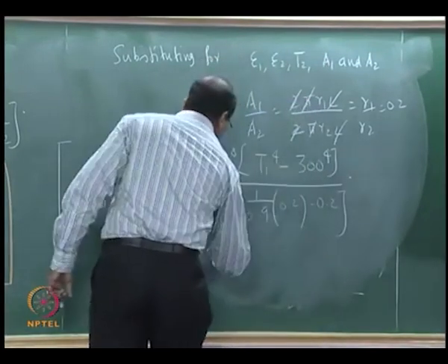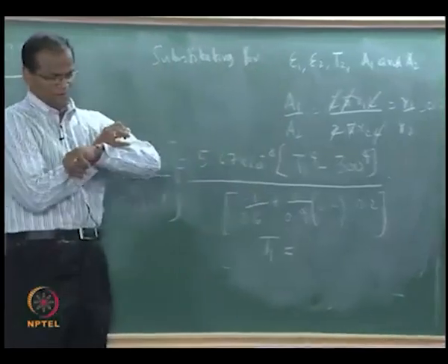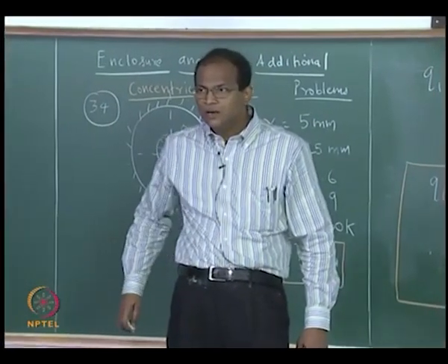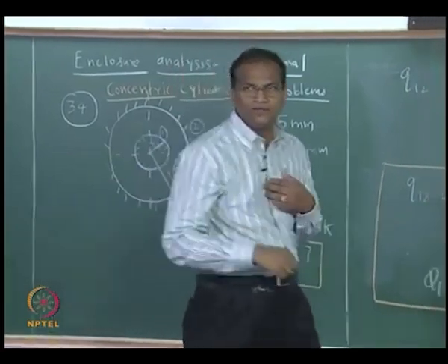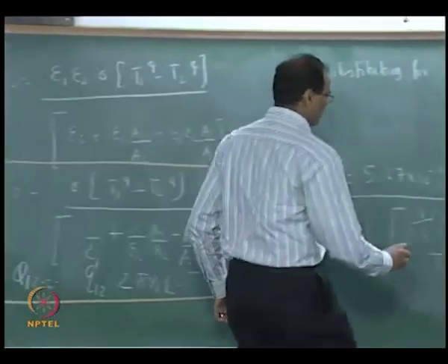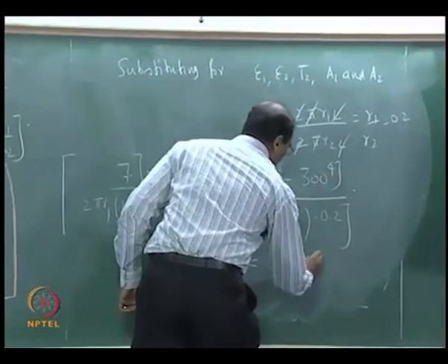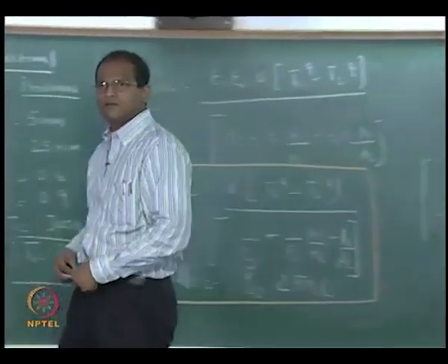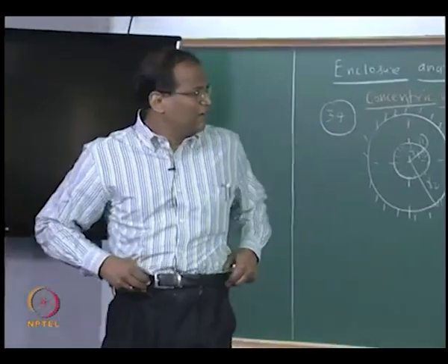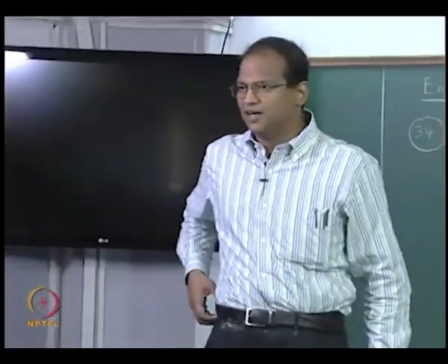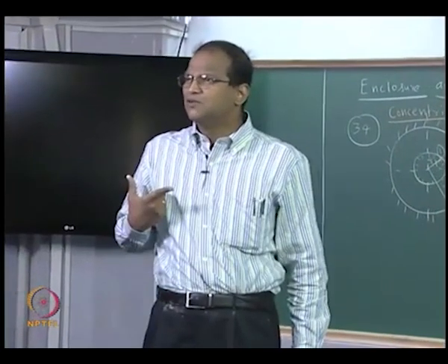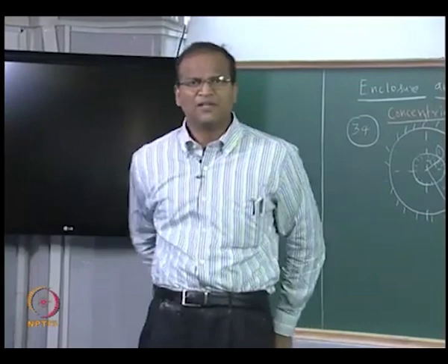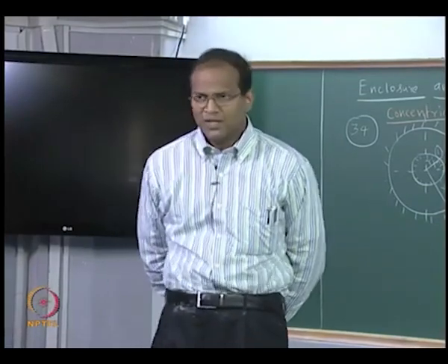T1 equal to 348, fine. Can a wire withstand the temperature? Alright, it can withstand. Suppose there we get 1343 or something, then we have to check our calculation. What is this 348 is how much? 75 degrees. 75 degrees wire can withstand. Okay, so there is no problem.